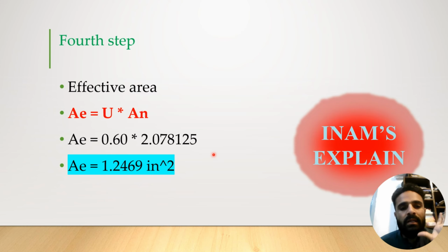So this was the whole lecture on effective area, on how we will solve a numerical on effective area. Only two things are required. The number one is the shear lag reduction factor, and the second is the net area. So I hope you got it.